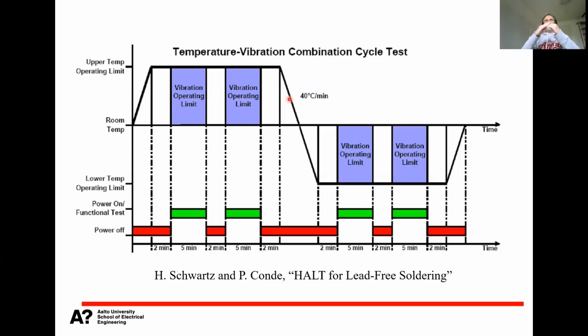Temporarily, the mechanical contact could decrease because of the combined effect of vibration and thermal distribution, and then your contact resistance increases. You see the problem only here or here, but you are not seeing it when the temperature has stabilized. Therefore, it is strongly recommended that you do the functional testing throughout the whole cycle, but that is not always possible. It depends on your measuring system, on your device, and so on.